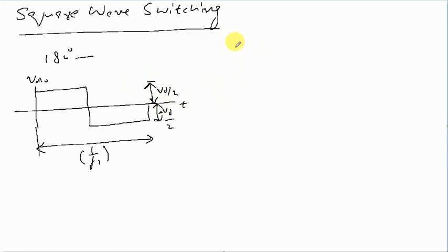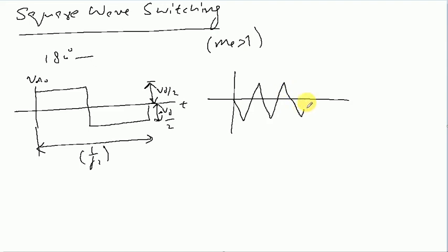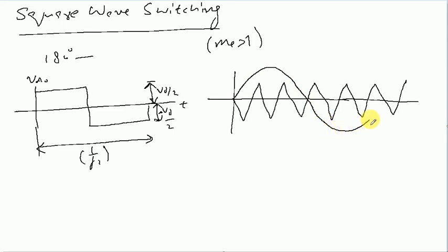So in this particular case, what happens is that the amplitude modulation ratio is made so large that, for example, if we have this triangular wave, the value of the sinusoidal signal is made so large that for this entire range, we can see that this is our control signal, and this is our triangular signal.